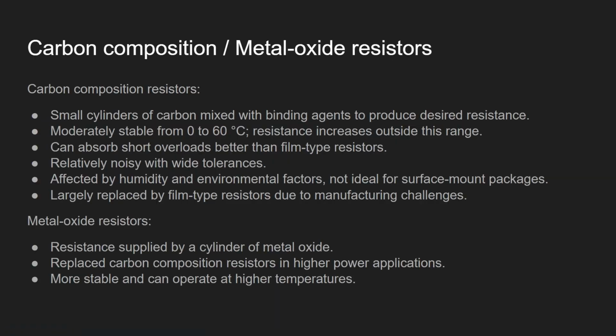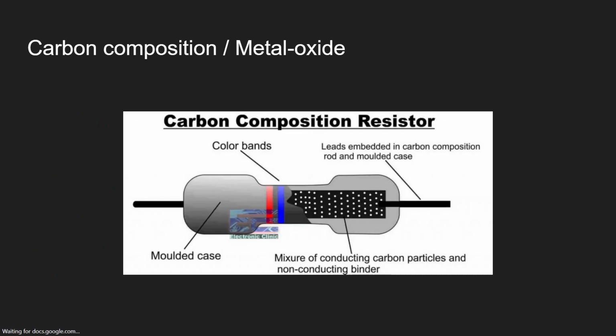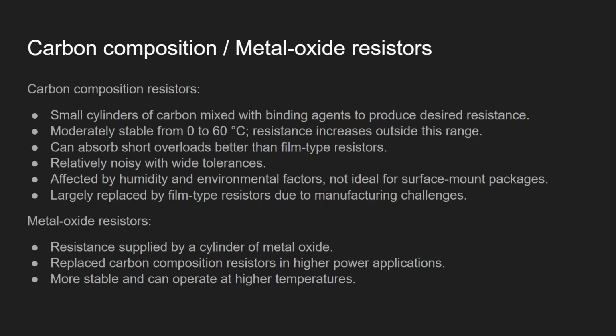But you may encounter questions like which resistors can be used as a dummy load. A dummy load is a device to prevent your signals from being emitted, to absorb all your signals. You can use resistors to make an environment of 50 ohm. How to do that, and which type of resistor should be used? This will be the kind of question. So you can see that it is the carbon composite or metal oxide.